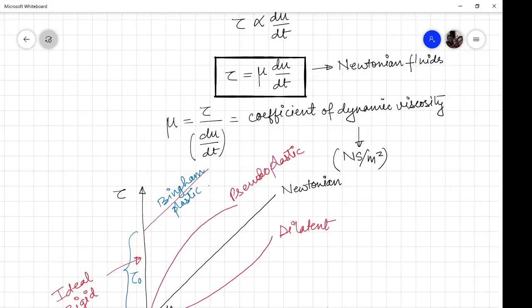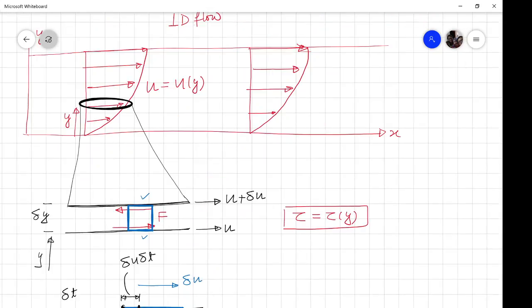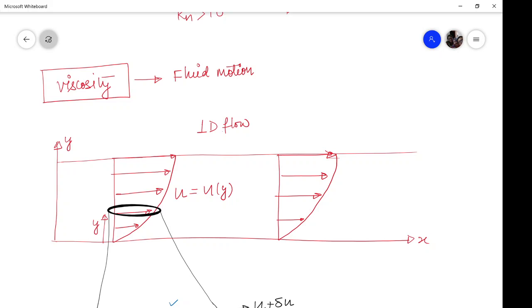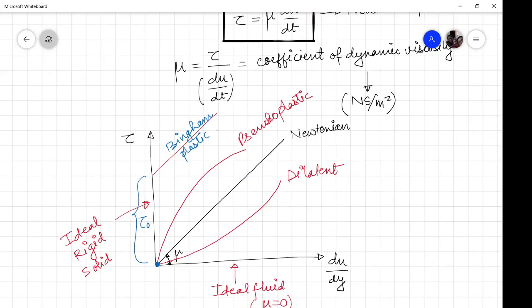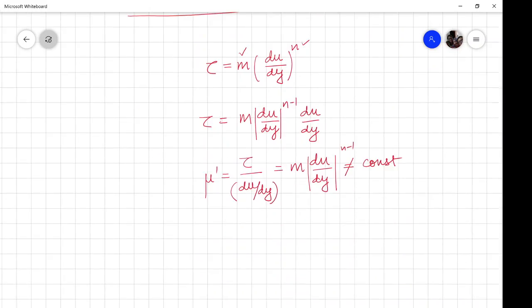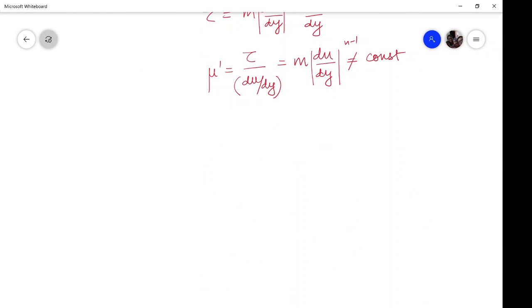So in previous case, we have seen that I have started the line, or I have started drawing the velocity profile from the base, that means from this surface, with a 0 mark. Why this? This is one of the fundamental boundary conditions known as no slip boundary condition.